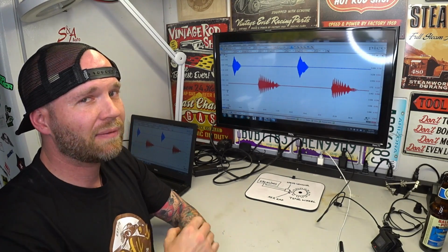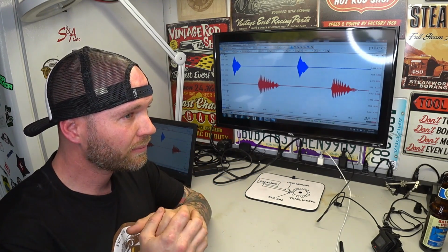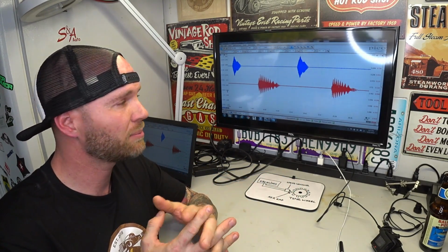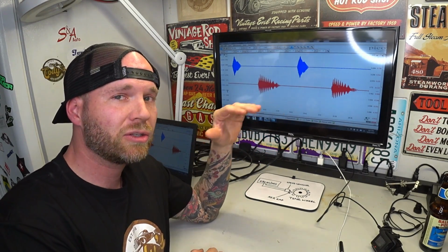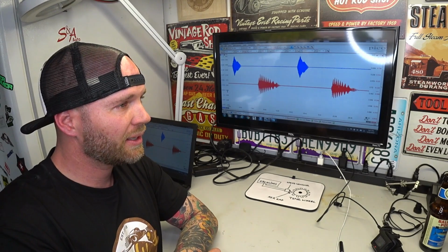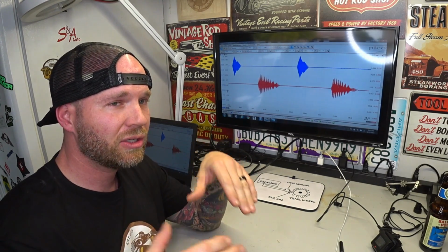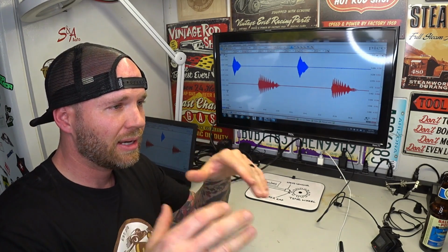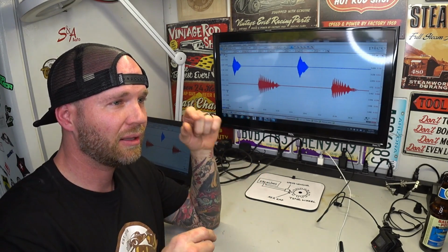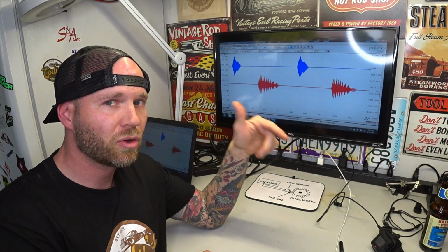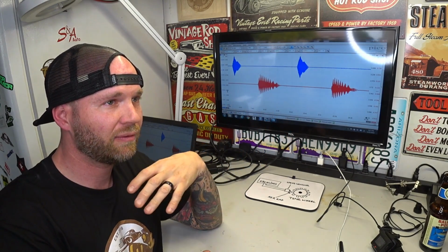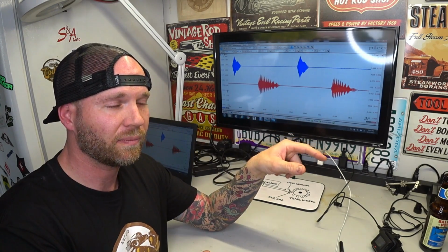But you have to think of it this way. And Scanner Danner has a great explanation for this. Using the Pico scope and going directly to the sensor and reading what the sensor is actually doing, what that sensor is telling the electronic brake control module, that is front door information. Okay, so that's information going into the module.